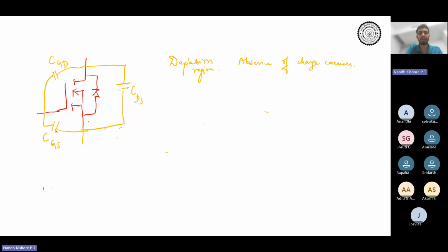As the device turns on and turns off, as the device blocking voltage varies, the capacitances are also going to vary. Because there is an n doped region and a p doped region, and there is a voltage blocking between them, a capacitance is going to form. So these are the junction capacitances of a device.